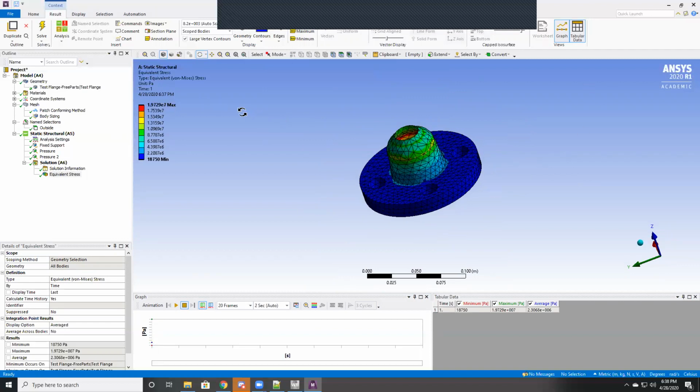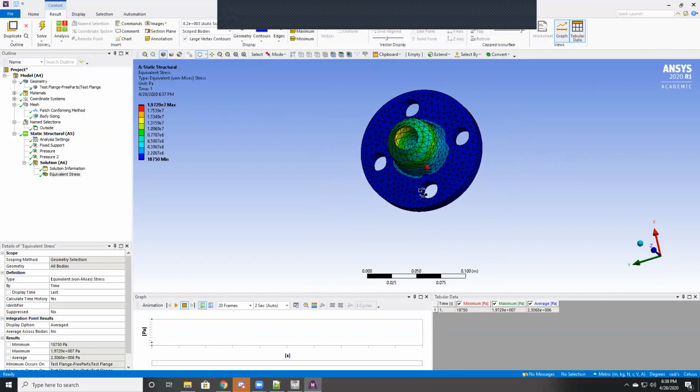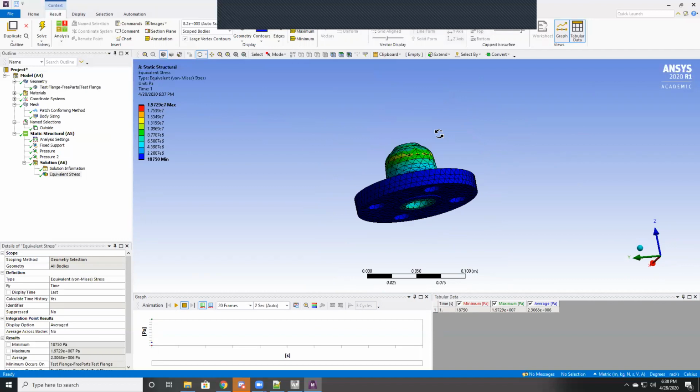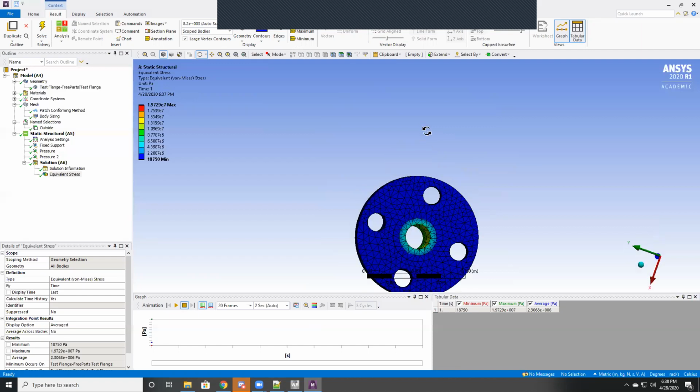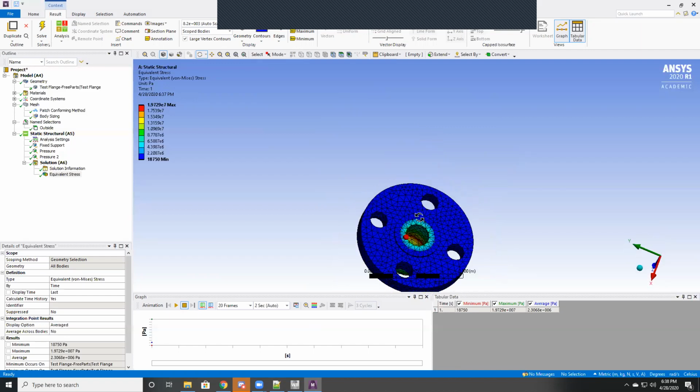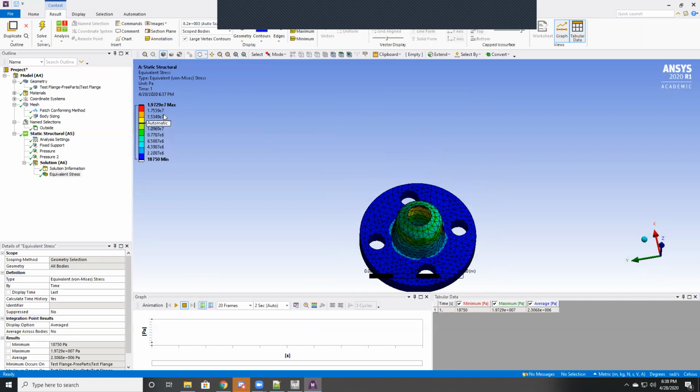That is about 20 megapascals for the maximum stress we're seeing. And stainless steel has a yield stress of about 210 megapascals. So this part is clearly within tolerances. Obviously, we expected it to be because that's its rating. But it's good to verify in some cases, but mostly just verify with parts that we're modifying in some way or that we are making ourselves.